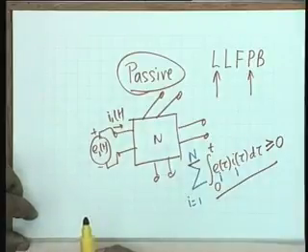Then it is called a passive network. You know resistance, ordinary resistance, capacitance, inductance, they are all passive. On the other hand, a negative resistance, a tunnel diode for example, is an active element because it can deliver energy. An initially charged capacitor is not a passive element because it can give out energy. So, initially relaxed network, if the energy integral summed up over all the ports is non-negative, then it is called a passive network. We close here.